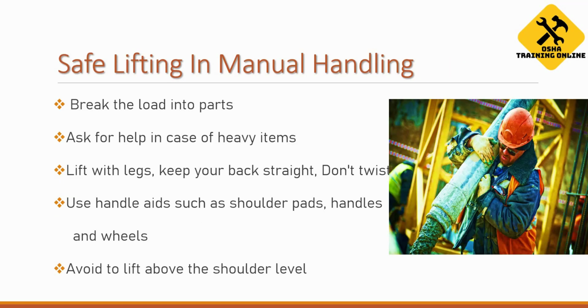Now, what is safe lifting in case of manual handling? What are some of the procedures which should be taken for safe lifting? So, break the load into parts. If there is a too heavy load, then divide it into smaller loads so it will be minimized in size. In that case, you will be able to carry it from one place to another. Ask for help in case of heavy items, as we have discussed in the previous slide.